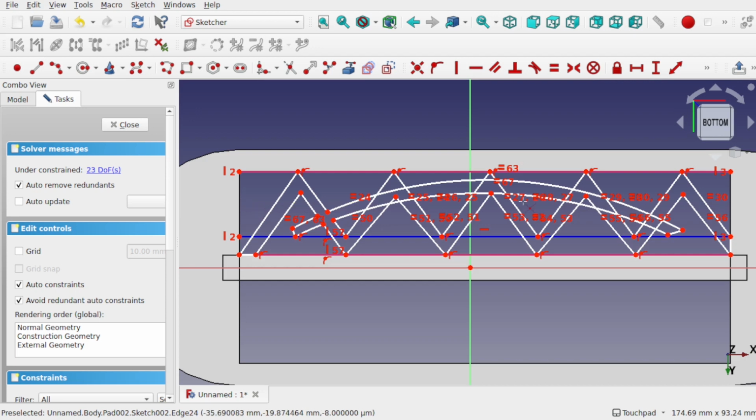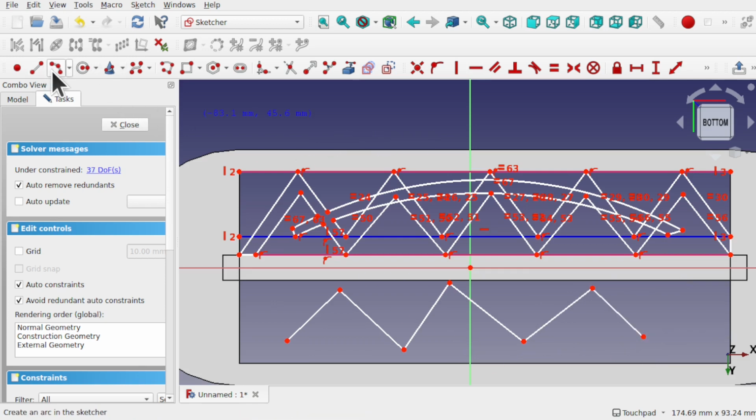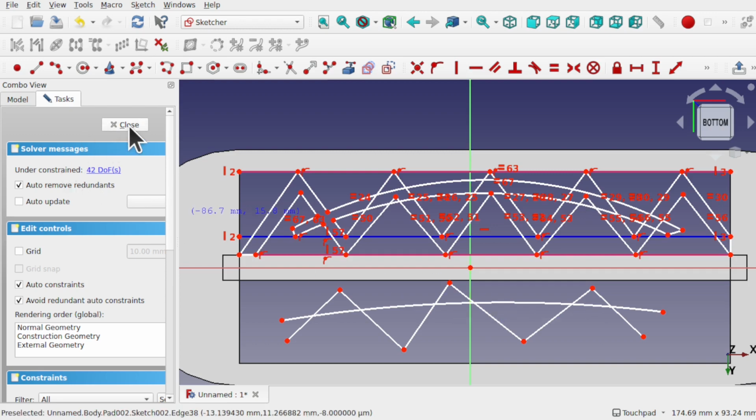If there was only a way to do this with just a single line, so for instance we created a geometry like this, and once it's all constrained up, you then can just add an arc like so, and FreeCAD will automatically thicken this. Well, there is, and this is where the Part wins over the Part Design.